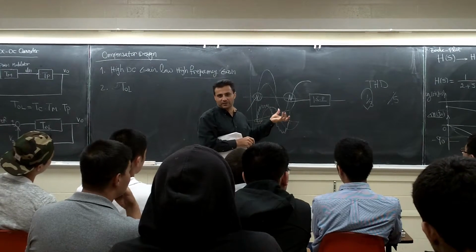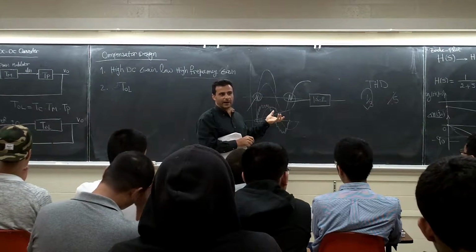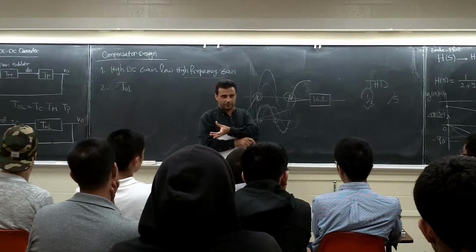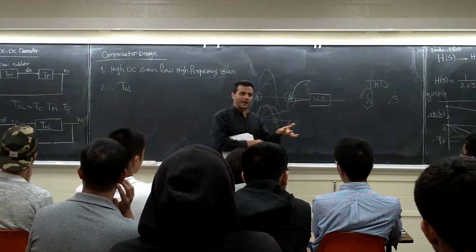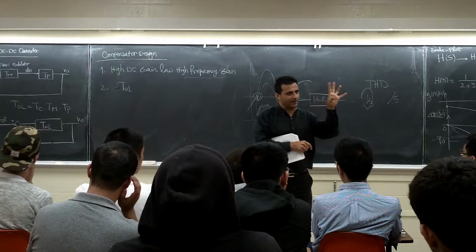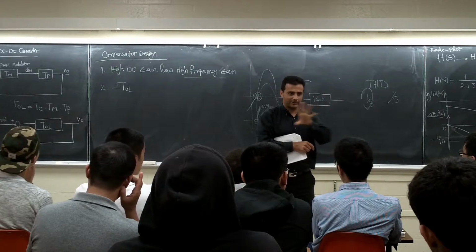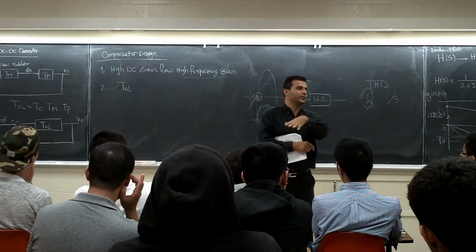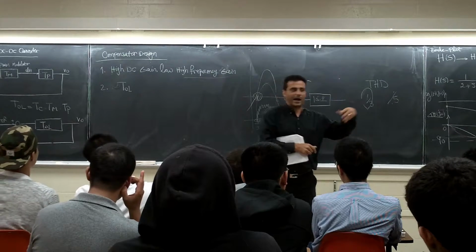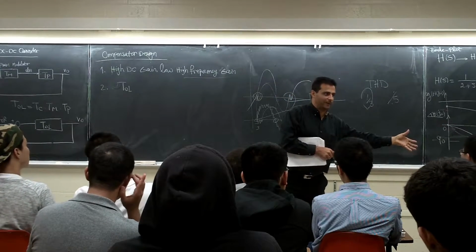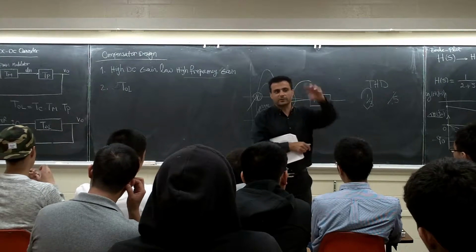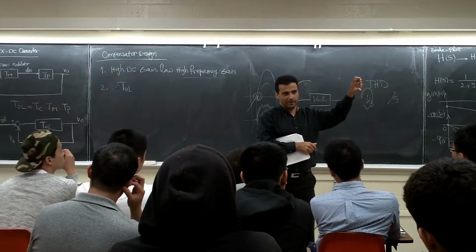See, the difference between a digital filter and an analog filter: an analog filter, you build it with parts. A digital filter, you build the transfer function, right? Both of them have a delay. If you look at it mathematically, they're the same thing. This one has a transfer function; you build it in your DSP with programming. The analog filter, you build it with RC, RLC elements. So basically, both of them have one transfer function at the end of the day.